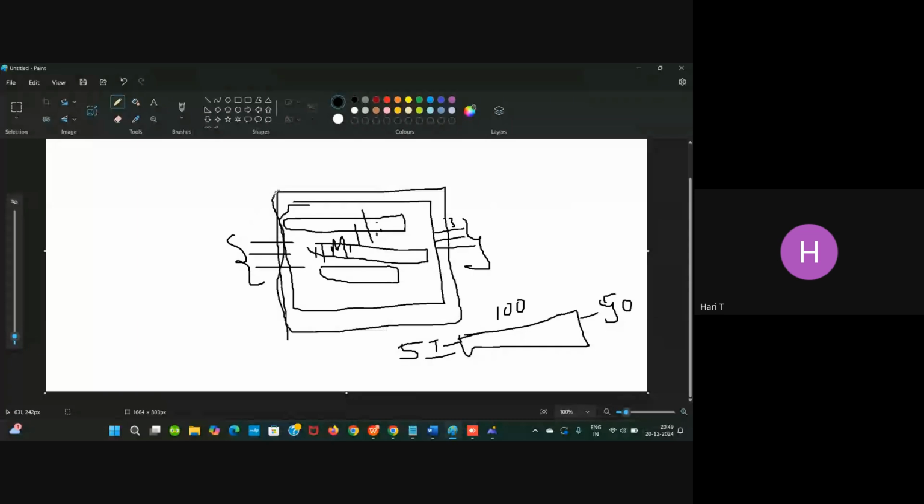Actually, this does not resemble the actual design. It is just a block diagram. What I was trying to explain is when you implement a DFT, there will be a formation of certain scan chains in the design. These scan chains are basically clock based. Depending upon the clock domain, the tool stitches each individual cell into separate chains.